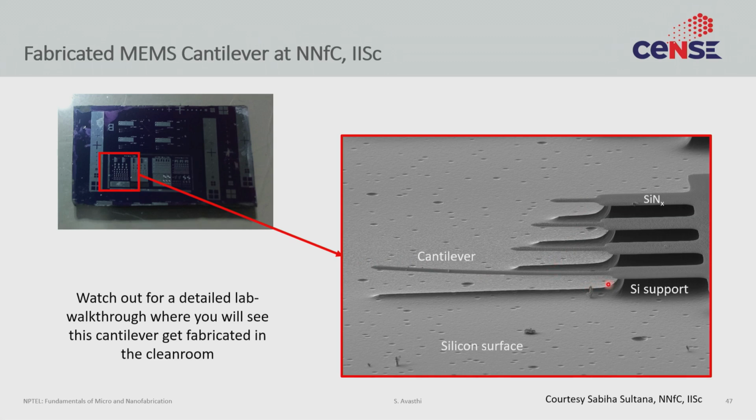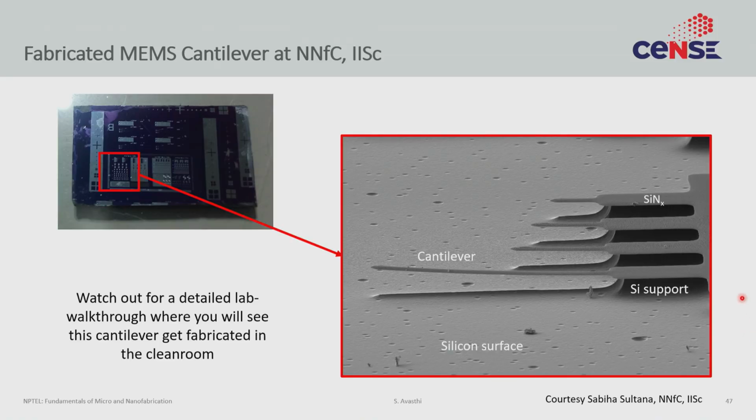You can actually tell that we do an isotropic etch by the shape of the etching that we are getting, remember? So we're getting this spherical or smoothish looking profile, not vertical ones, because we are doing an isotropic etch. But you also see evidence of the original anisotropic etch that we did. So again, if you look at the SEM from this side, you actually see relatively flat walls. So yeah, it's a combination of anisotropic and isotropic etch, and you can get the cantilever.